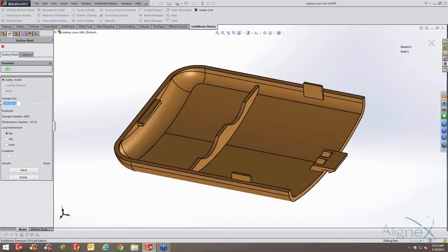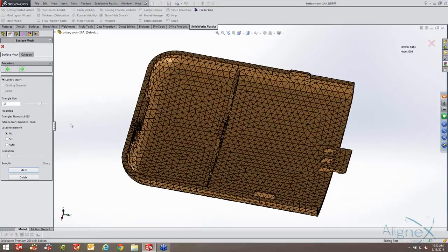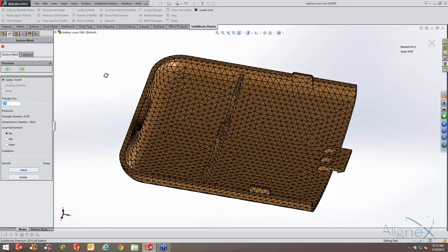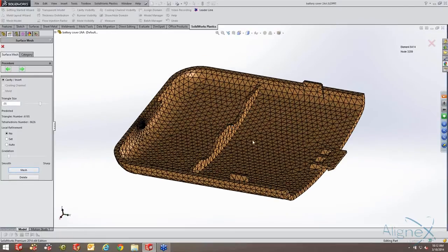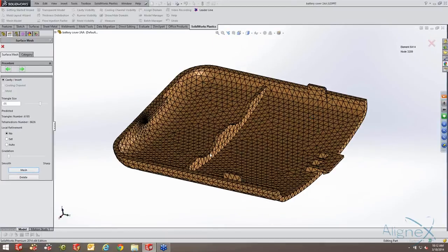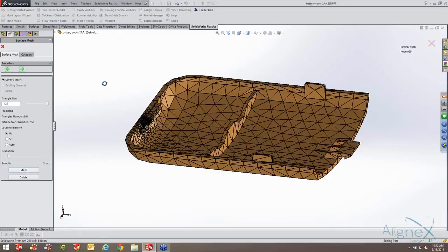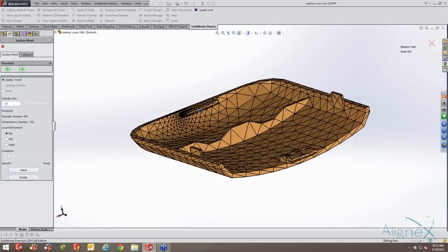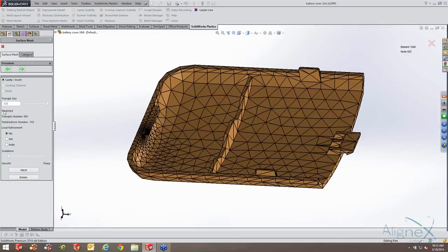Now we get into our meshing module here, where we generate a mesh. You can see on the screen, I put in 50 thou. We are in English units right now. What I've got to look at here is, does it pick up the detail that I need outside and inside? I do have some other options available though. If I loosen this up to, let's say, a quarter mesh, you can see it becomes really jagged on the details like you see inside of here and outside the wall. It looks more like a chamfer than it does an actual fillet.